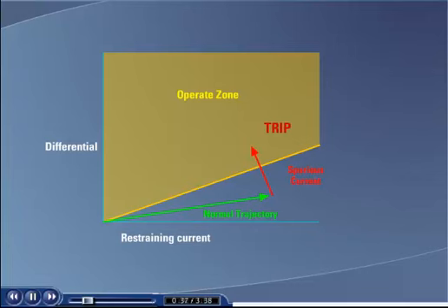Note that even when a fault occurred that results in deep CT saturation, the CT would initially step down the current correctly. The operating point's initial trajectory will be such that it departs from the pre-fault point position and will shift to the right, as was the case in the previous example. Once the CTs go into saturation, the measured current, and therefore the restraining signal, decreases. This causes the operating point to shift trajectory up and to the left. With enough saturation, the operating point could enter the element's operating region, resulting in a maloperation.